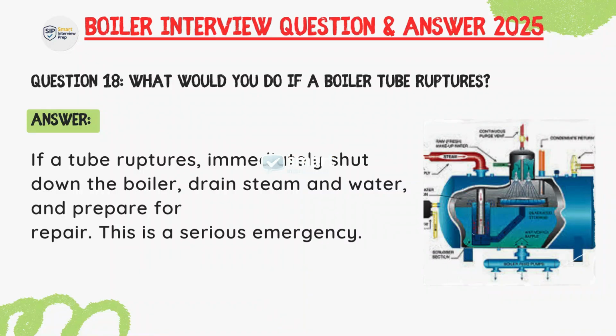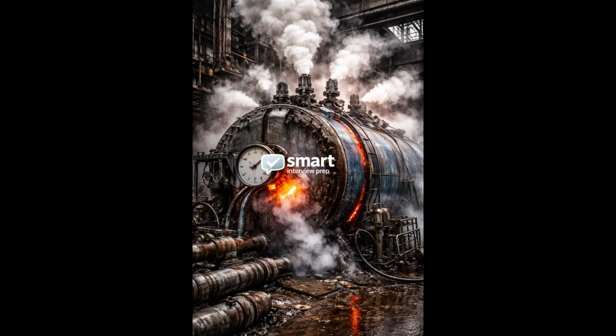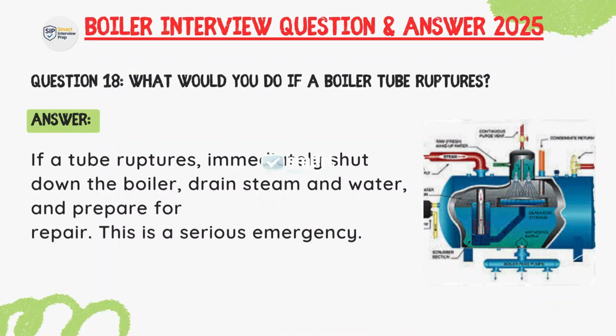Question: What would you do if a boiler tube ruptures? Answer: If a tube ruptures, immediately shut down the boiler, drain steam and water, and prepare for repair. This is a serious emergency.